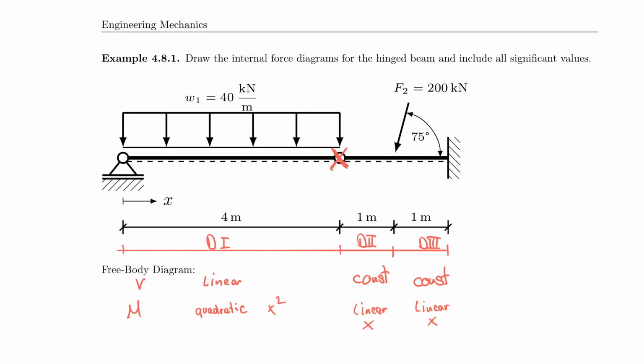I'm going to make my life very easy here because I have a cantilever on the right side. All I need to do really is find what's called RAY on the left side, and once I have that, I can just work my way from left to right. So let's find RAY first. Actually, that's very simple in this case. RAY is really only dependent on what goes on in this subsystem here.